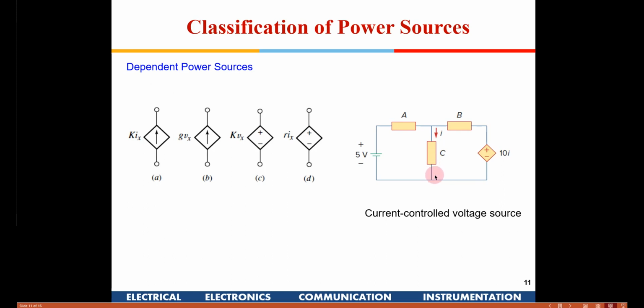So that 1 millivolt, if I put an amplifier and put the output of the amplifier here, then this voltage will become proportional to the current which is flowing out here, right? So those kind of circuits, although in symbol it is shown out here like this, this itself will be a small circuit, and it can physically be realized. Okay, there is no problem in that.